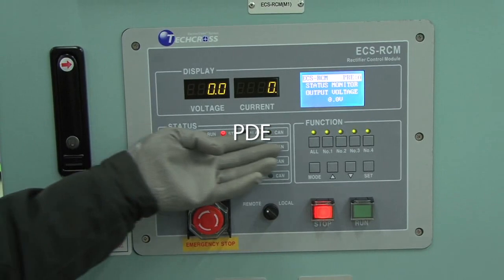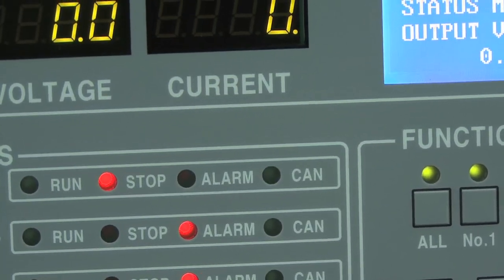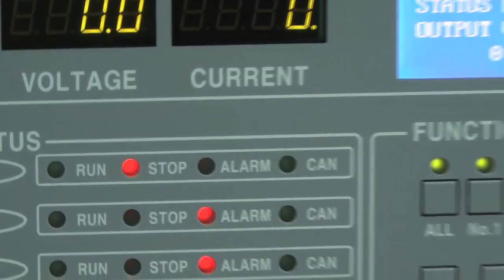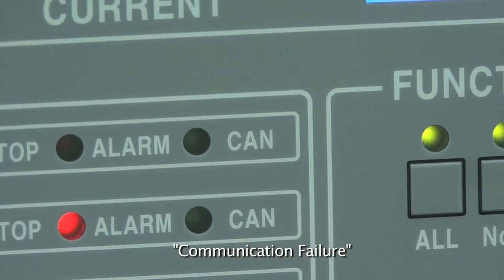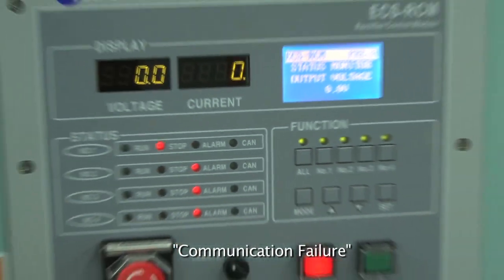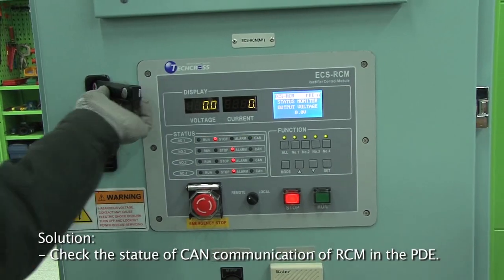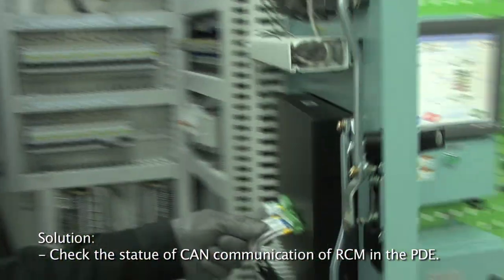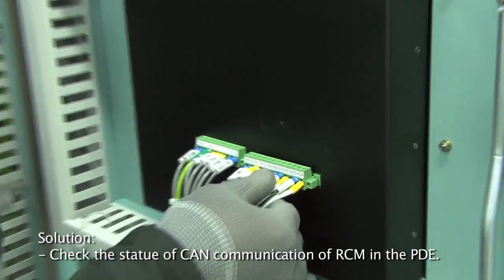2. Troubleshooting for each equipment. 1. PDE. Problem. ECU shuts down 1 minute after alarm message, communication failure, appears. Solution. Check the state of CAN communication of RCM in the PDE. Normal communication mode.